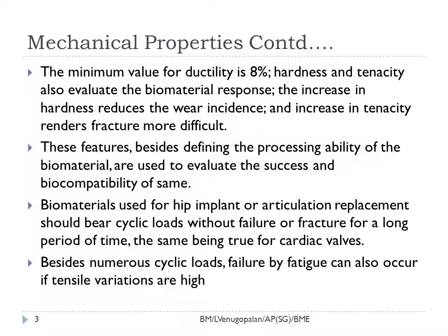Now, for these kinds of material, it is okay to have a ductility that is around 8%. However, hardness and tenacity have quite a lot of importance because hardness would reduce the wear incidence and tenacity would make fracture difficult for that particular material. So, if wear is reduced and the probability of fracture is also reduced, then the life of the implant is increased.